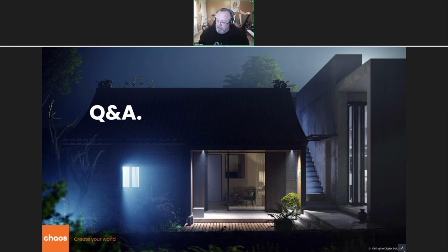We had a question about the ordering of decals and whether naming has any effect. The answer is no. You can name them any way you like. The ordering is purely controlled in the 3D scene as to which one I'll say is on top. In our case, we were doing it on a flat road surface, so it is literally on top, it's height.